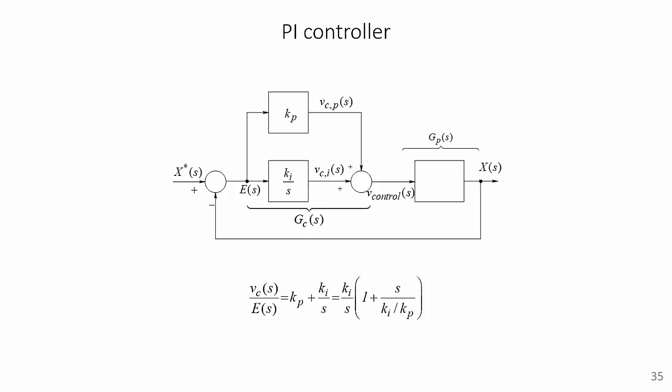So in any real world implementation, before you use a differential controller, you'd usually have a filter that filters out the noise signal, or you would restructure your algorithm in such a way that an integral and a differential component cancel out. You rewire your control algorithm so that you don't end up differentiating an input signal which can be noisy.